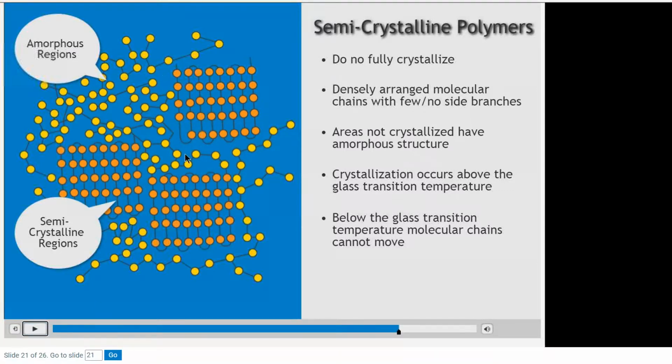This is very, very important. So there's two different structures, amorphous and crystalline. So just think about if you don't know which material you're molding, it probably will have an effect on the quality of the part. So please make sure to know what you're molding and to set up the process in accordance with the material you are molding, because the process will be different.